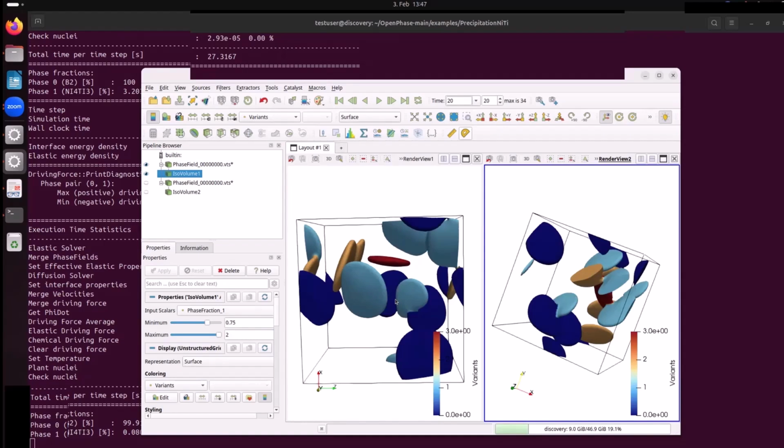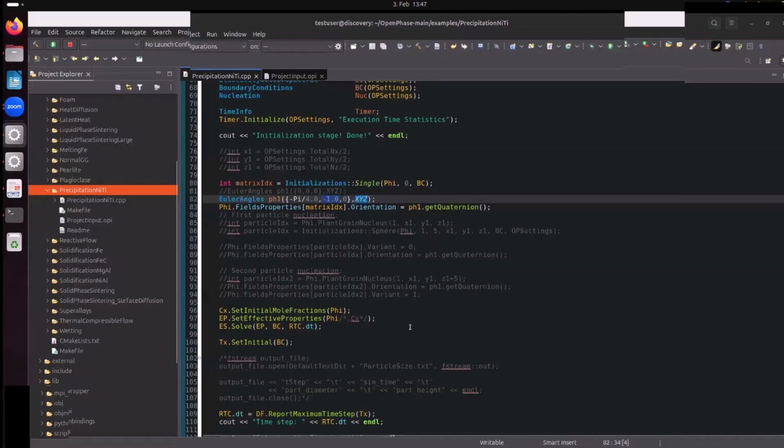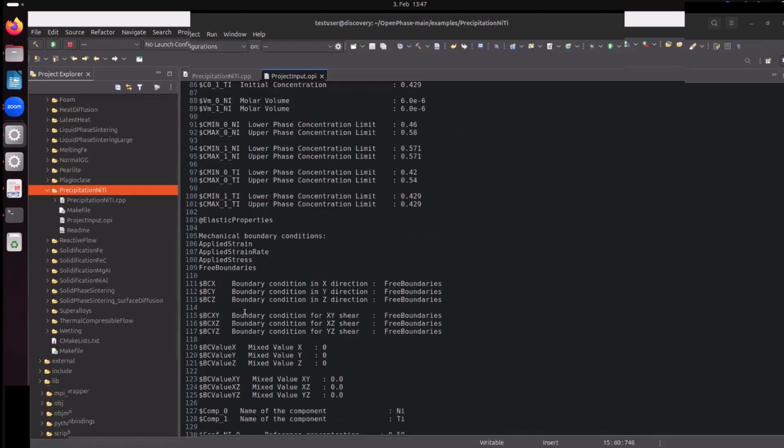So, and then I also prepared the simulation with loading, but I think we have already run out of time in this tutorial. So what you could do in the project input, for example, instead of the boundary, you could just specify, for example, let's say -500 megapascal stress, and run the simulation again after you've saved it.